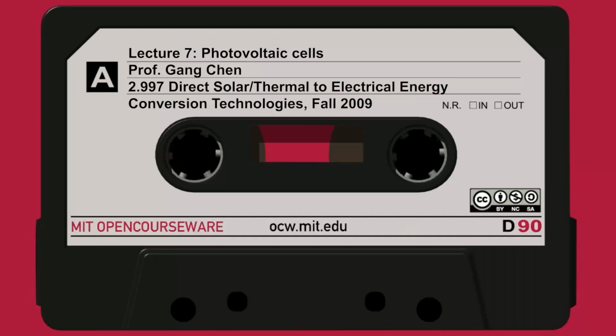And look at where the photon goes. Of course, at the interface there is reflection. You don't want the reflection, so you minimize that with anti-reflection coating and surface treatment. But once you get into the material, you almost have no other way to control this profile anymore. It's the material's intrinsic absorption. This is the absorption coefficient, and the intensity decays exponentially.